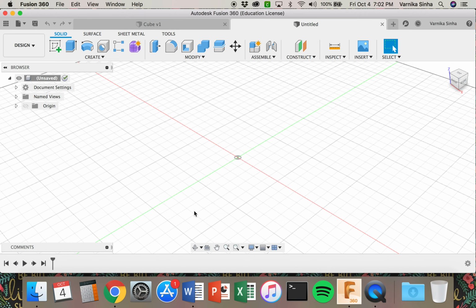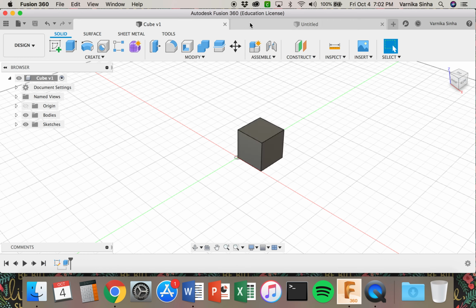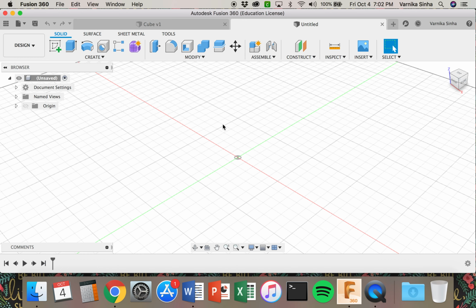So now what are we going to make? Well, we're going to make a sphere. Okay? So what was I talking about before? Remember in the cube, I was like, should we extrude or should we revolve? So the first thing we have to think about is, what is a 2D image of a sphere? It's a circle, right? So say we made a sketch of a circle, and then we extrude it. So we added a linear dimension. Well, what would that be? It would be a cylinder then, right? Because we're adding an extra dimension.